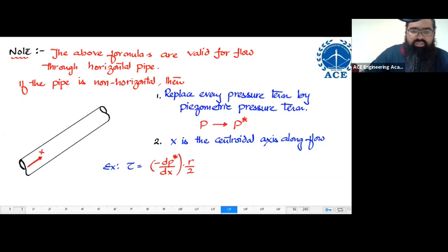Very good question, Shankar. Bernoulli equation is valid for inviscid fluid. Then what about this particular case? In this case, Bernoulli equation is valid. Only thing is, you are supposed to write head loss. If you remember, we have defined Bernoulli equation for real flow, and in real flow you are going to have head loss involved. You're just going to include head loss over here. Please try to follow these points. If you follow these points, then the next class will be very easy for you.